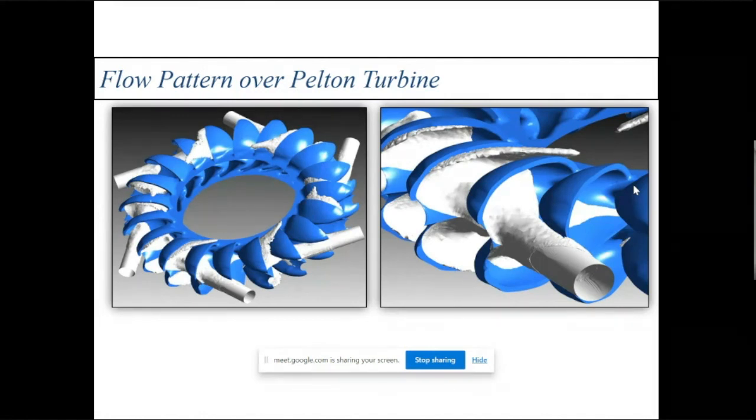And in doing the Richardson analysis, there is a well-defined procedure, where we have to simulate three cases: coarse, fine, and very fine. Then we see how the output is sensitive to the mesh density. Then we get the quantification. That is the well-defined approach, and for 99% of the papers accepted in this area, the reviewer wants to see the Richardson method analysis.